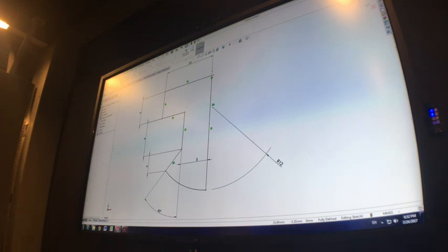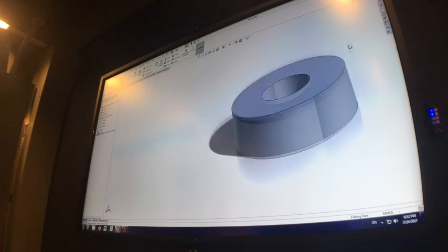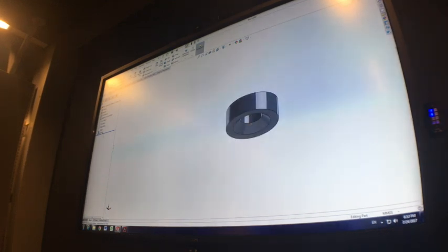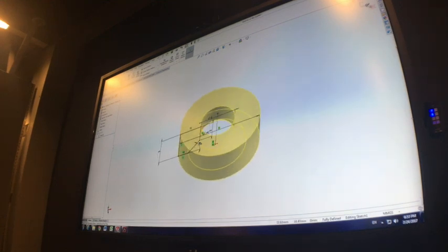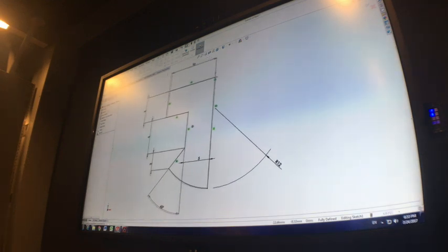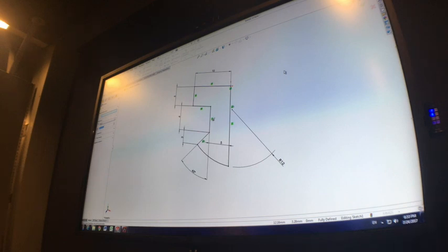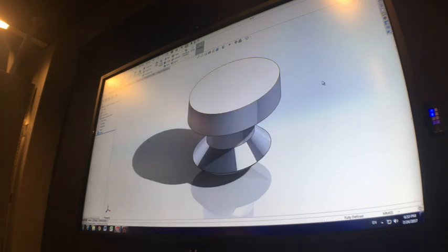So we're going to revolve that. Now this revolves a little bit different to the one we did for the washer. The difference is with this sketch, there's a construction line in the middle, and so there's a hole when we revolve the router. In this part, there's no construction line. So when we press revolve, SOLIDWORKS waits for us to tell it what line to revolve around. Okay, so we need to indicate that we're going to revolve around this one. Click that, and then we get our preview. Press OK, and that revolves complete.